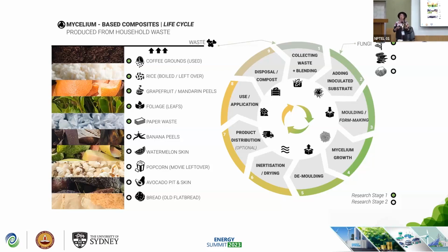Then you let it grow for 2 weeks, and it forms really firm matter that you can then dry, demold, and use. These are the materials that I tested so far for producing these mycelium bricks or objects. The coffee one, I drink a lot of coffee, maybe not as popular in India, but I did manage to grow 95% coffee bricks, and they perform really well.